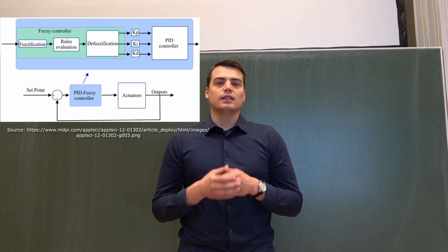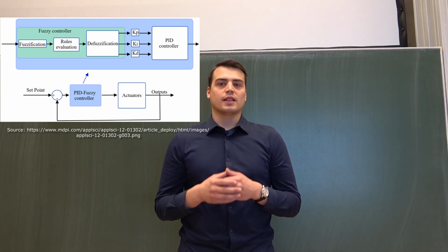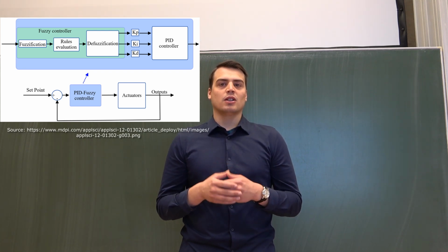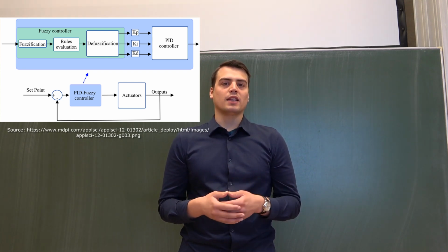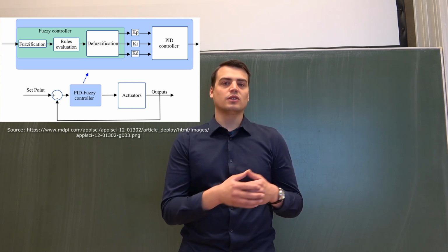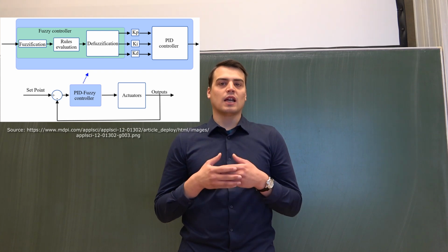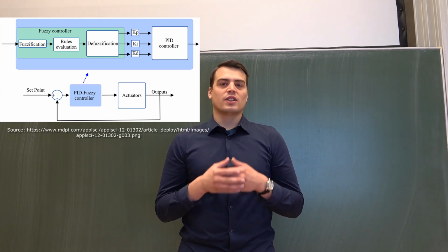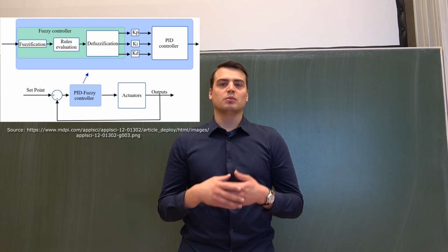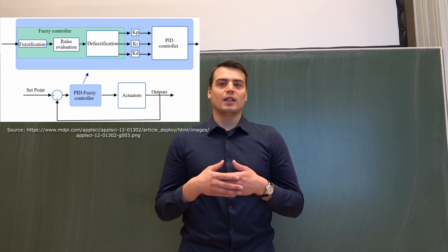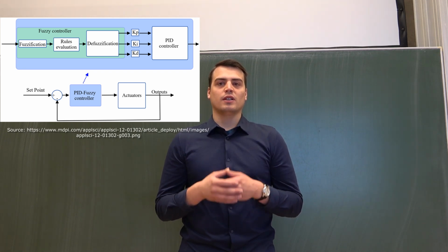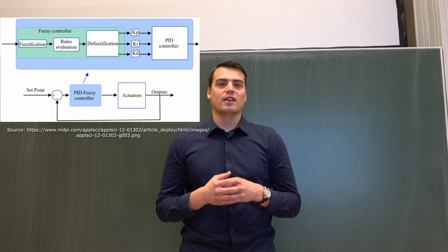This technique is often used as an add-on to other control mechanisms, especially in the outer control loop to manage position and trajectory tracking, while the inner loop handles attitude stabilization. For example, in a study of a low-cost quadcopter, FLC was employed to adaptively adjust PD controller gains to improve trajectory tracking performance.